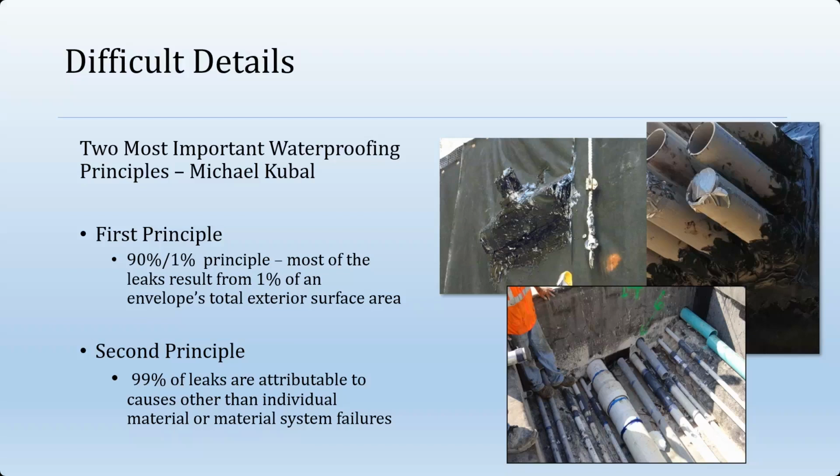The problem I have with that is, if we treat it like a pitch pan, and a number of manufacturers can and do accept a pitch pan using a heavy bodied mastic around the pipes to effectively waterproof them. If the pipes are touching each other, are we going to be 100% sure that mastic is providing or creating a seal in between the two pipes where they're virtually touching each other? That's anyone's guess. And I'm always getting a little bit leery of those types of conditions.